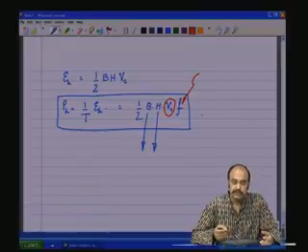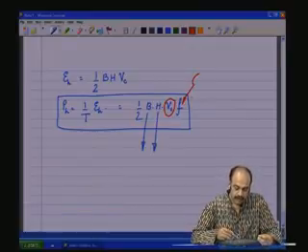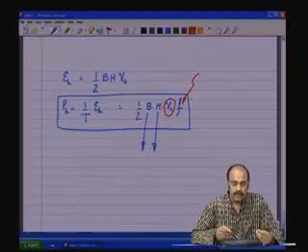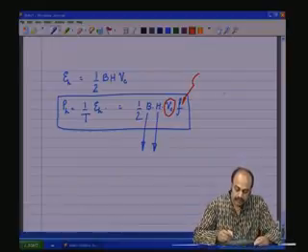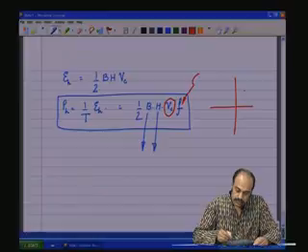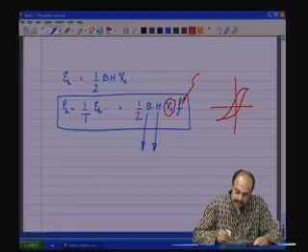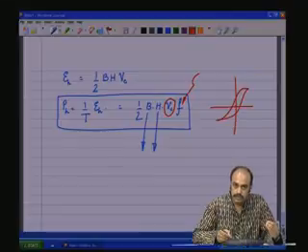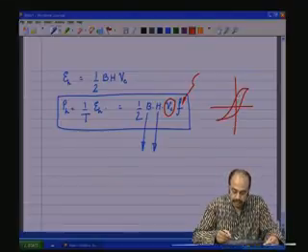This is also in keeping with what we understand, because we are talking of the hysteresis loop. Now, one traversal of this hysteresis loop means this area is covered, and that amount goes into what is called the hysteresis loss, which is unrecoverable.